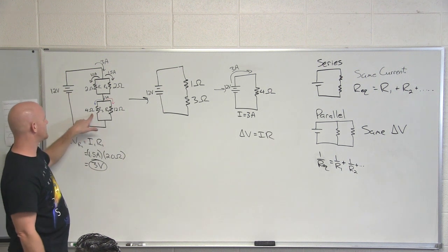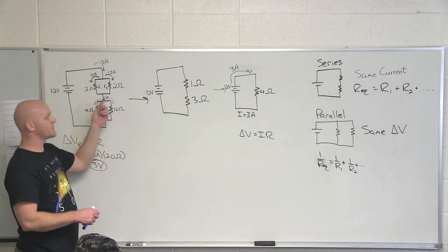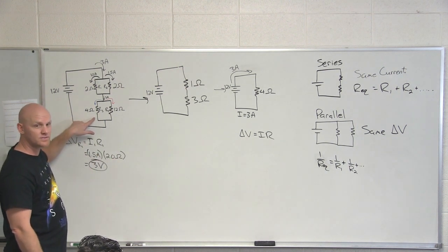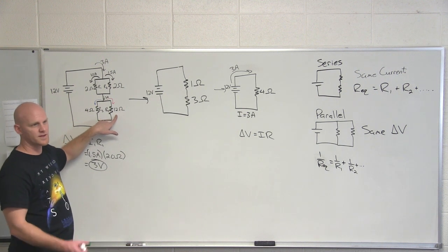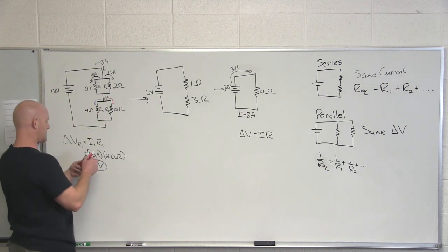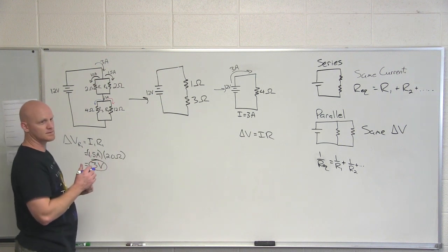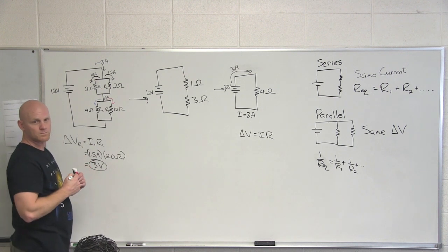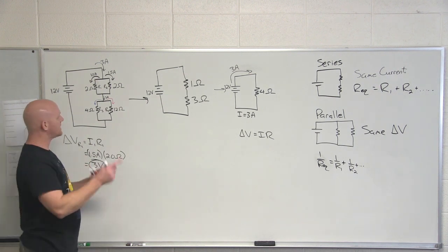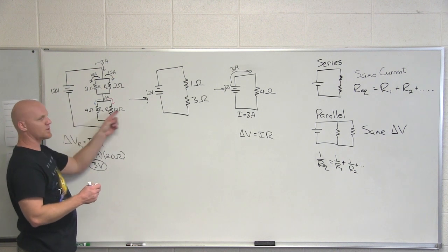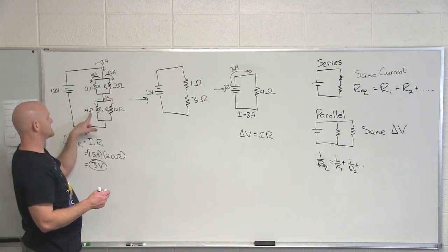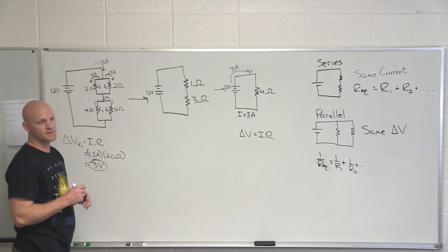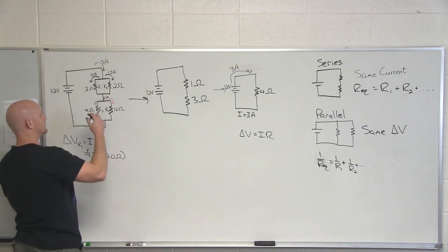So in this case, 12 ohms to 4 ohms, that's a 3-to-1 ratio, and we'll break up this 3 amps into 4 equal parts. 3/4 of that 3 amps goes on the path with less resistance, and 1/4 will go on the other side. So what is 3/4 of 3 amps? So you said the more current goes on the one with less resistance, and so it's not directly related anymore. This is only in this 3-to-1 ratio. So this side is 1/4 of the total if you added the two, but it's going to get 3/4 of the current. And what is 3/4 of 3 amps?